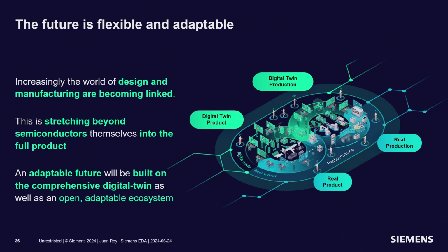Those materials and substrates need to support the integration of a very large number of chiplets on dimensions of the order of 0.5 meter by 0.5 meter, with thicknesses that go down to 2 microns for the substrates, with 7 to 10 metallization layers on each side, with much more aggressive densities for the through material vias, and much more aggressive dimensions for the traces and metallization layers.